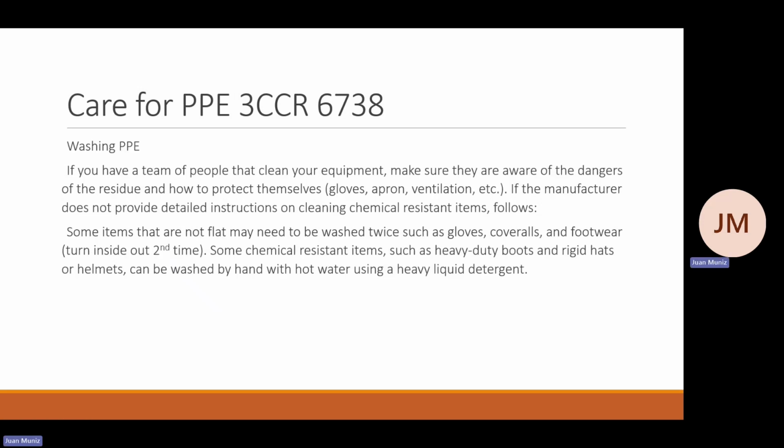Washing PPE. If you have a team of people that clean your equipment, make sure they are aware of dangers of the residue and how to protect themselves, such as using the proper gloves, apron, and proper ventilation. If the manufacturer does not provide detailed instructions on cleaning chemical-resistant items, follow the next steps.